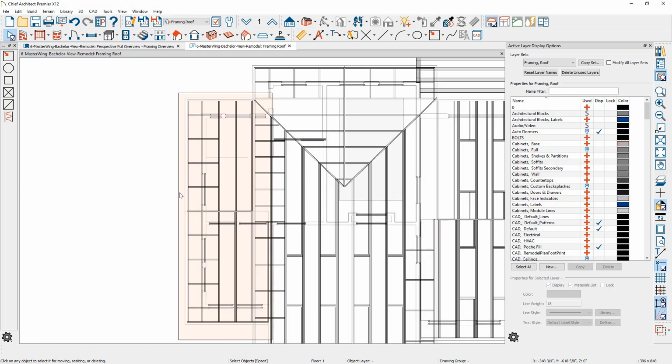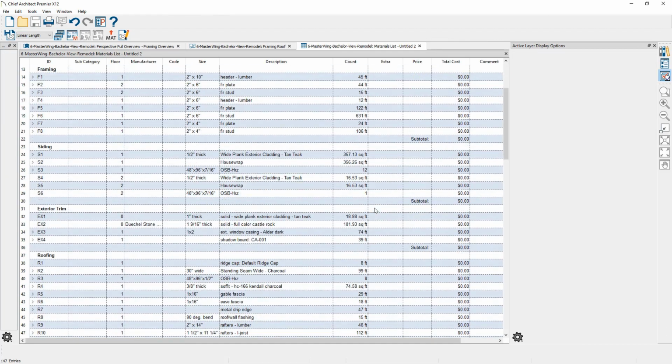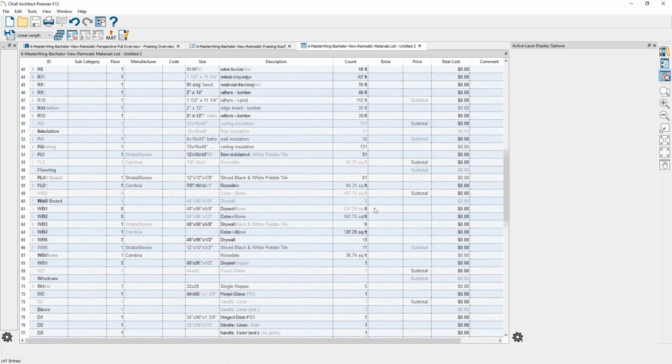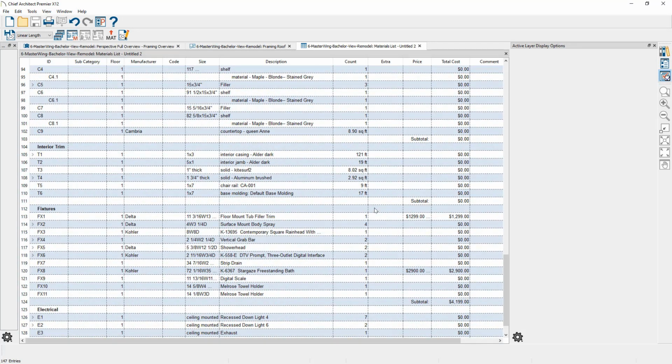Once the materials list polyline is created, select it. In your lower edit menu is the option now to calculate materials from the polyline. This will generate the spreadsheet-like format of all of the categories that we specified in that materials list by area through all floors. There is an option to edit the active view. Let's go ahead and take a look at what that means.